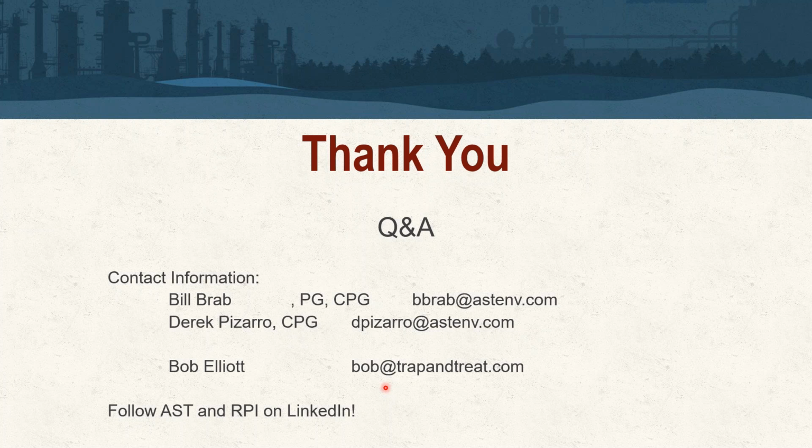Yeah, I can take that. So the 6-inch completion we're talking about is specific to the open borehole and rock, so the actual drilled borehole. And as we've noted before, the well construction, or the specification that we need, are open boreholes for our particular purpose. So for the characterization, we want to be able to insert tools within that borehole, whether it be geophysical tools, downhole camera, or this packer assembly for the purpose of aquifer characterization and analytical testing.